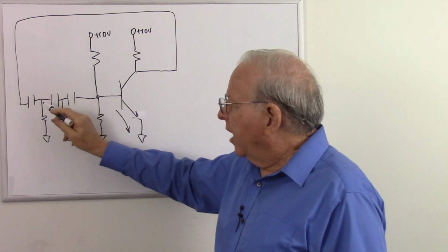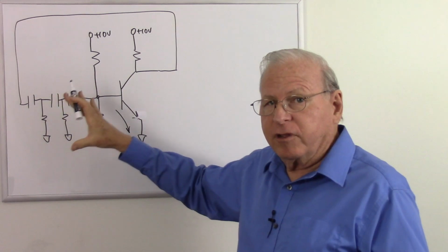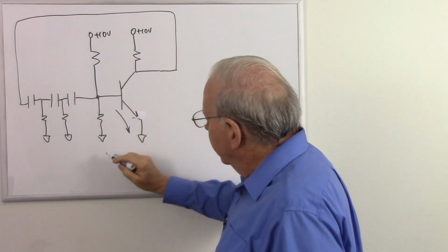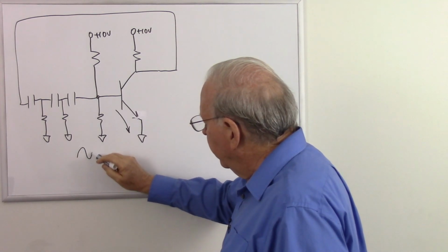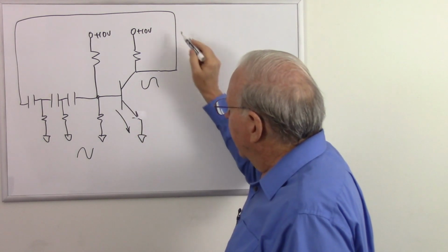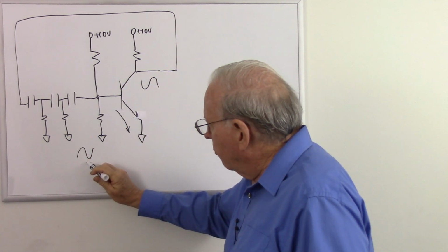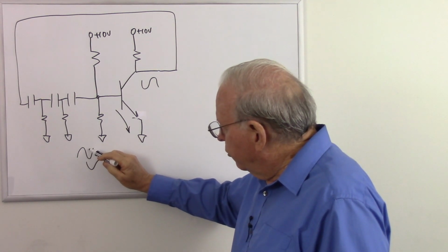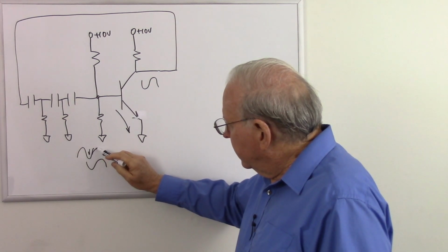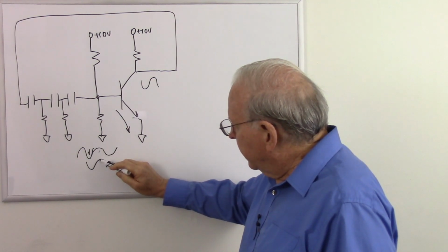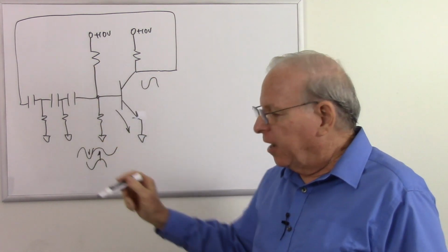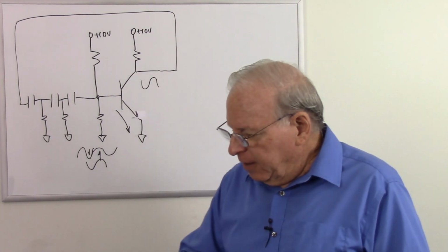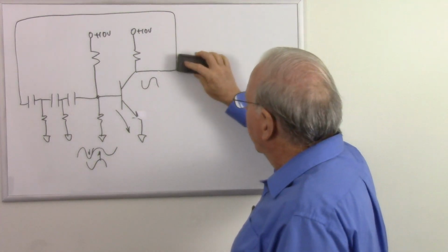And so we designed this so that the time delay at the frequency we wanted this to oscillate was such that we got our input. I'll put that right here. Here's our output, but the time delay caused our output to be late. Now when this is going down, that's helping push it down. And if we continue, when this is going up, that's helping push it up. So now we have that positive feedback. So that was the phase shift oscillator, but is there another way we can get our positive feedback?